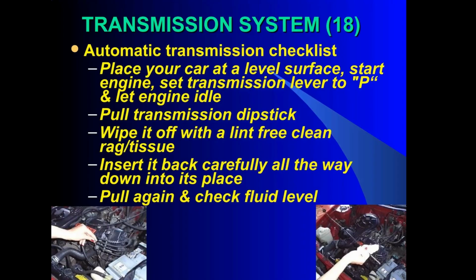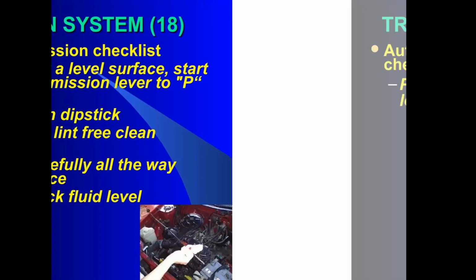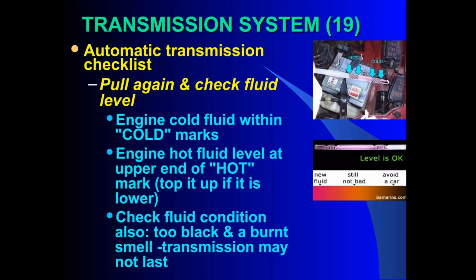In dry conditions, the torque applied to the wheels is limited by the engine and gearing. An open differential always applies the same torque to both wheels, which is limited by the amount of torque that will not cause the wheel with the least traction to slip. When traction is low, the amount of torque is limited by the greatest amount that will not cause a wheel to slip. This is a problem with open differentials. A limited slip differential, or LSD, allows more torque to be transferred to the non-slipping wheel.